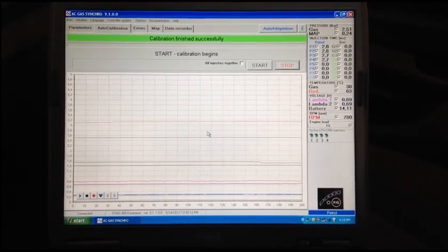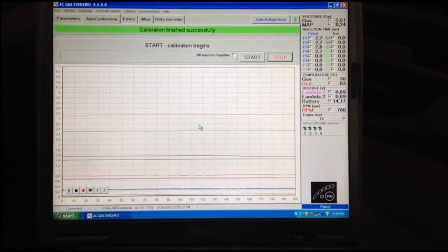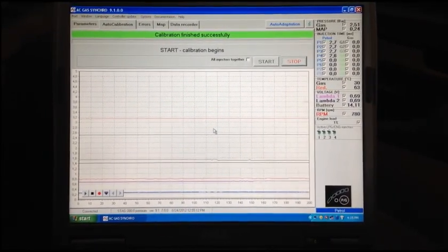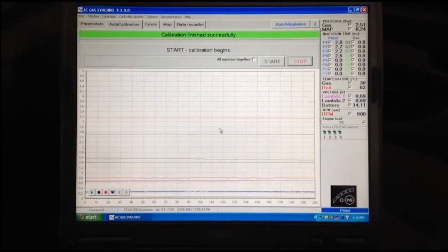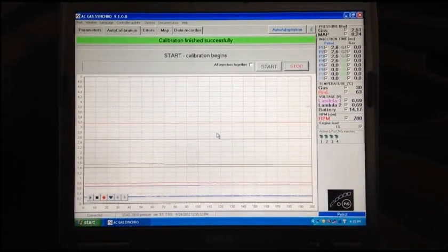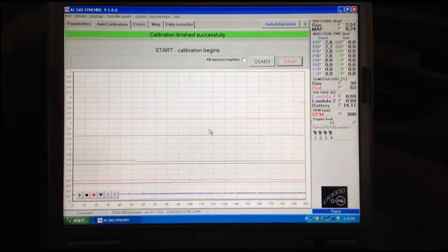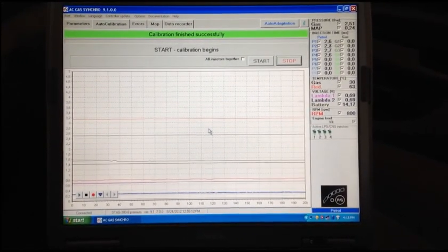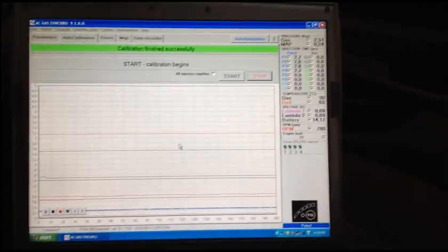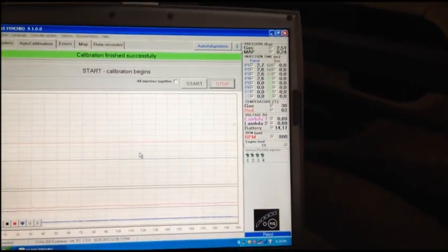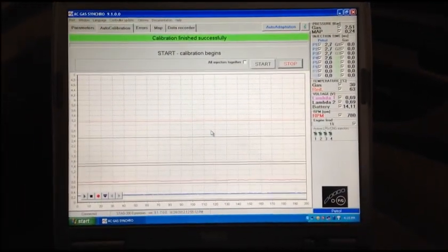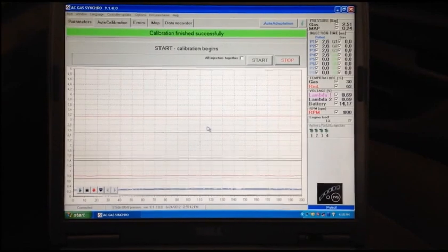Because if it's too high, it's having to use too much pulse width to drive your CNG injectors at idle. It's going to know whenever you really get up under heavy load, it's not going to have enough gas flow, so you need to size up. Or the other problem that you can get into is if you drilled out your nozzles too large, or you've got your pressure turned up too high, the pulse width at idle for your CNG injectors is going to be too small. They don't work properly at anything under 3 milliseconds.